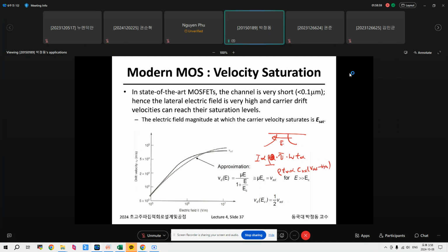And this velocity, previously it was VGS minus V threshold divided by L. Now it is just V set. It doesn't change depending on VGS. It is fixed. Which means ID is only proportional to VGS minus V threshold, not VGS minus V threshold squared.